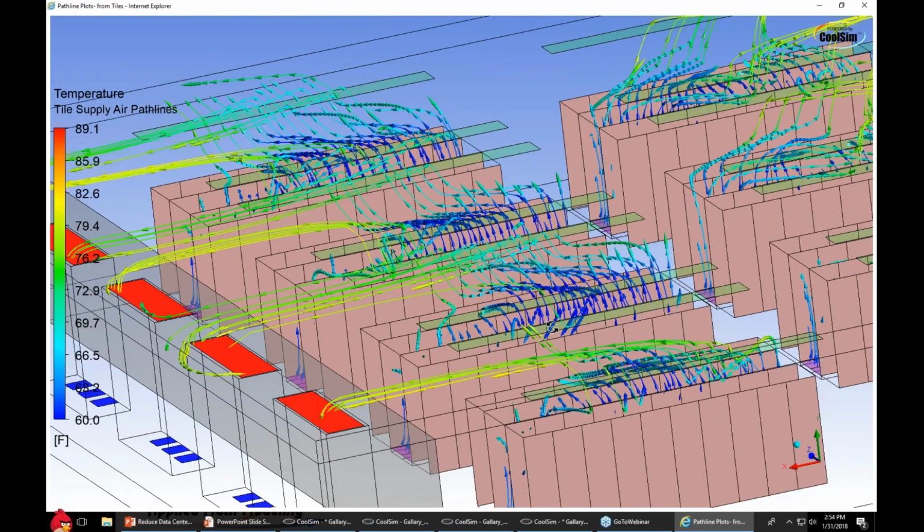What is the maximum rack server outlet temperature that becomes an IT operational problem for rack servers in critical data centers? Gene again. Well, what happens here is the delta T tends to be 25 to up to 30 degrees. So if you've got a 70-degree inlet temp, which you'd like to have, then your outlet temp is going to be 110 on some of these servers, and that's getting close to beginning to affect other stuff in the return path. So a 30-degree delta T is not uncommon. It is what people are running today, particularly in these high-density servers.